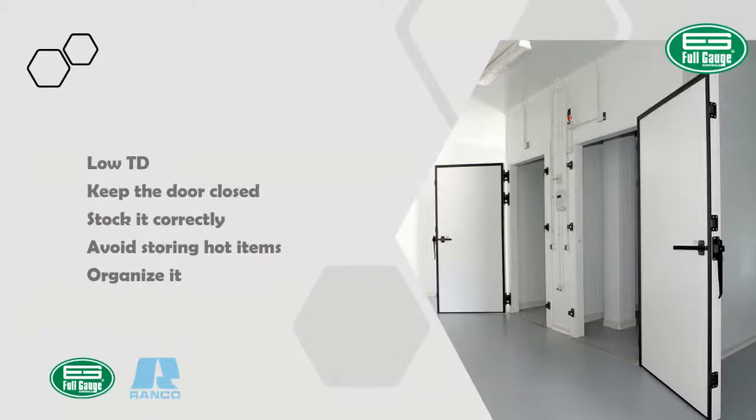Another nice tip for reducing frost buildup is to avoid storing hot items. So for instance, in restaurants, when you have a hot pan coming out of the kitchen, especially on freezer applications in low temp walk-in boxes, ideally you would take that hot pan and leave it in a refrigerated space, let it cool down before it enters the frozen space, your low temp device. So that's another good alternative to reduce ice buildup.